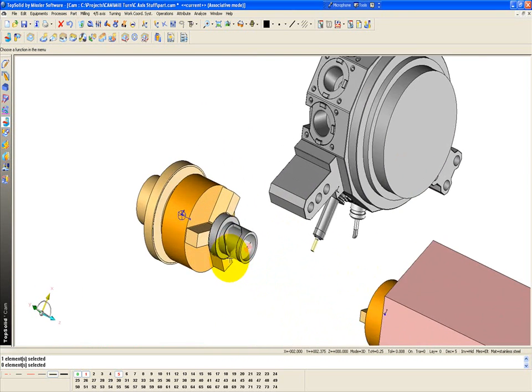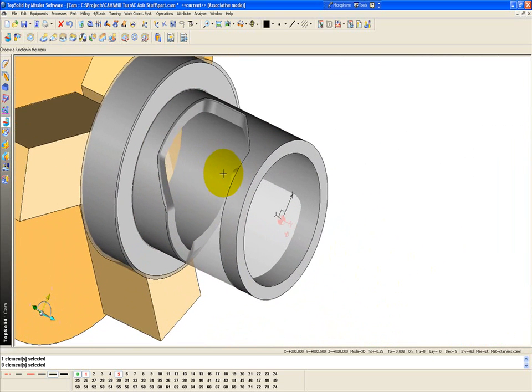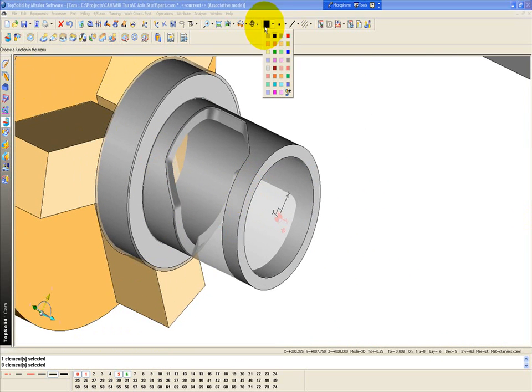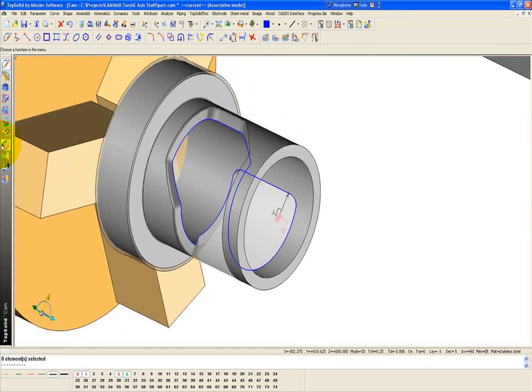is I'm going to activate a layer, and I'm going to get the boundary curve I need. To do that, first I'm going to go down to, I don't know, layer 6, make that current, and maybe name the layer just so I know what's on here, and I'm going to say this curve for C-axis pocket. Okay, and I'll do this as a different color. And I'm just going to go to copy edge, grab edge path, and I'm going to select the bottom inside edge. Okay. From here, let's go back to turning.